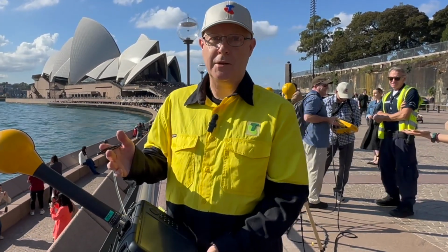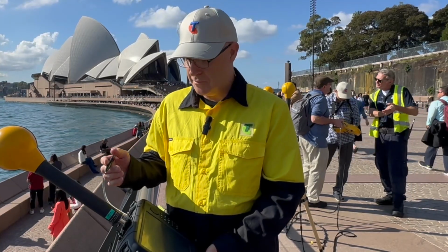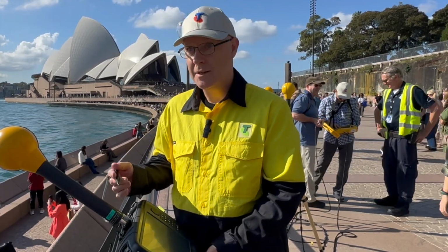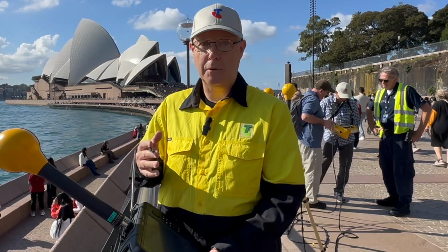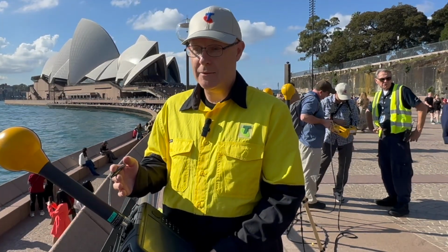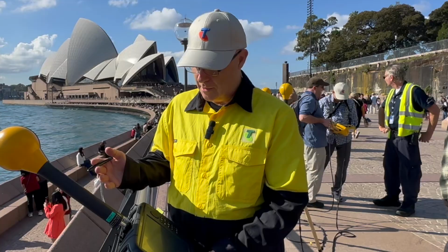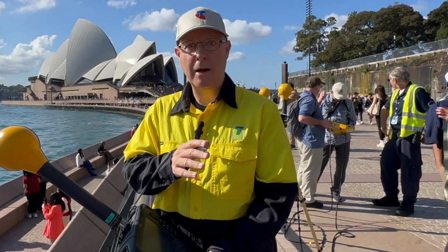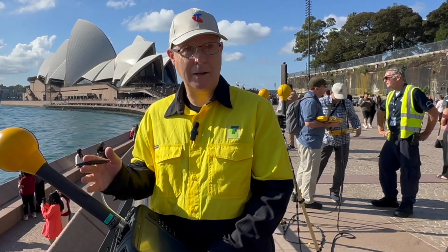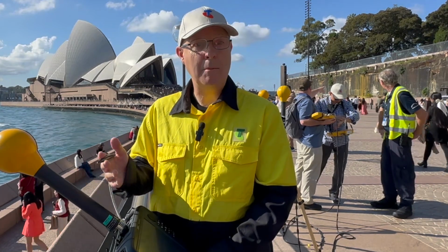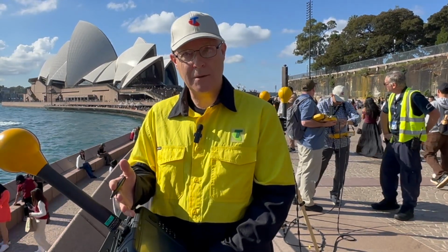Now, we're road testing the new Signal Shark from Narda. This goes from 200 megahertz to 8 gigahertz. What we're doing today is we're looking at all of the mobile bands, and there's a couple of options we've got on this unit. We can either look at the channel power across all the radio frequency bands and look at the average and the maximum.